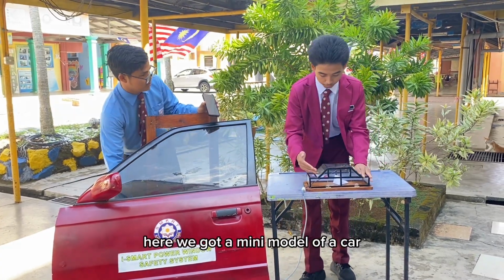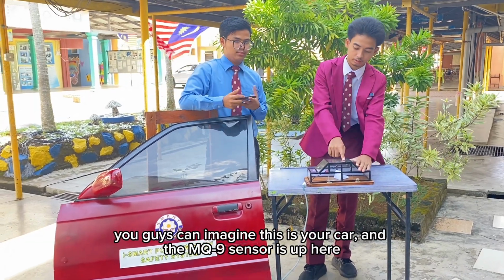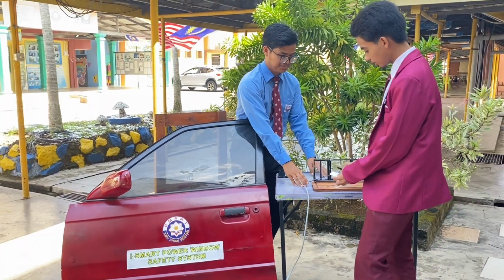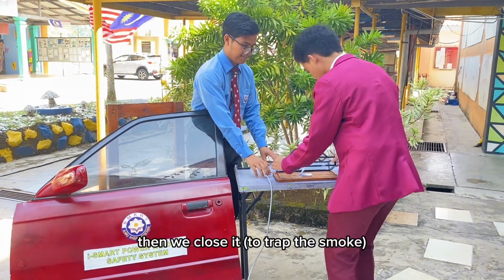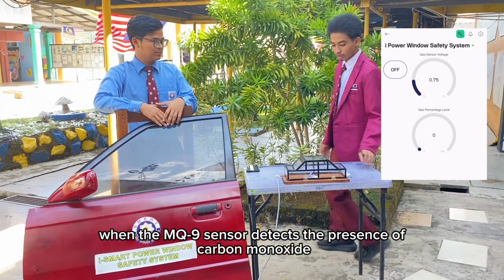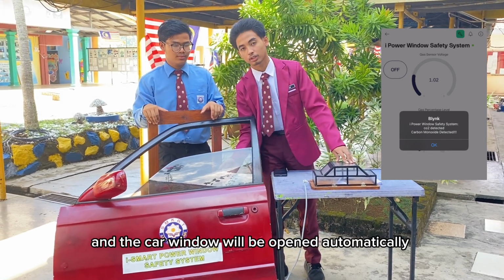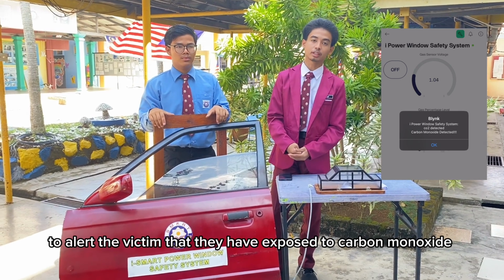And moving on to the next problem, it's about death caused by carbon monoxide. So here we got a mini model of the car. You guys can imagine this is the car and the MQ9 sensor is up here. So how does the system work? So we just simply burn a paper. And then we just close it. And when the MQ9 sensor detects carbon monoxide, it will send data to the microcontroller and the car window will be opened automatically and the buzzer will buzz to alert the victim that they have been exposed to carbon monoxide.